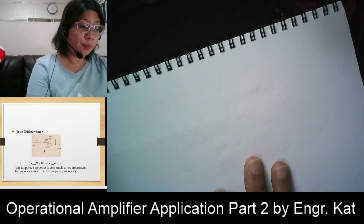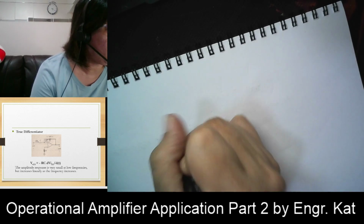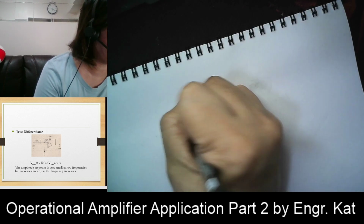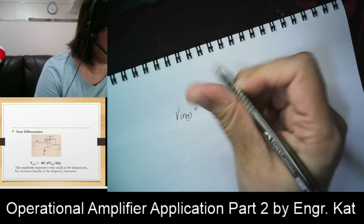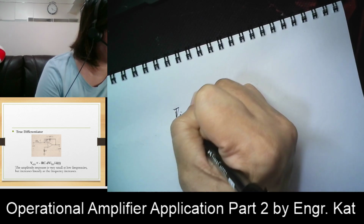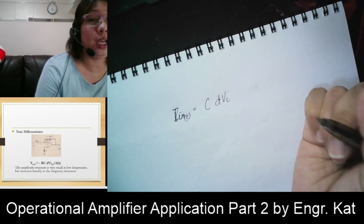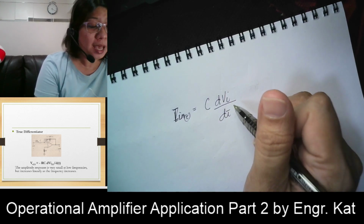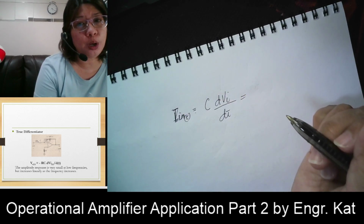For our input, that is a capacitor, so your input current is equivalent to C multiplied by the change in your input voltage divided by your change in time. That is also equal to the output current, which is also your ICT.